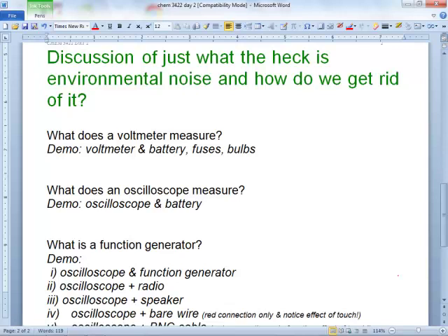So which one is a 9-volt battery? Would this be DC or AC? What would you guess? Is the voltage changing over time? Well, if you wait a really, really long time, it's dying on you. But the point is, it's supposed to be staying at 9 volts all the time. So make sure you have this over on the DC part. And it's got all these little scales. So this is a cheapo version. On expensive ones, you just put it on the V straight line and it'll auto range itself. But this one, you know that's 9 volts, so let's put it on maybe the 20.